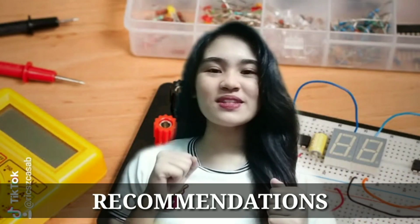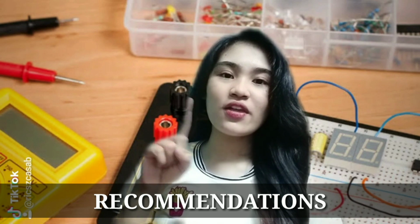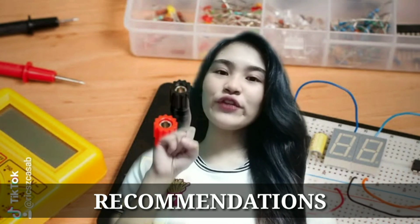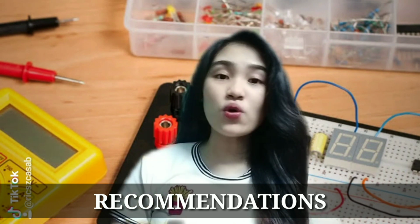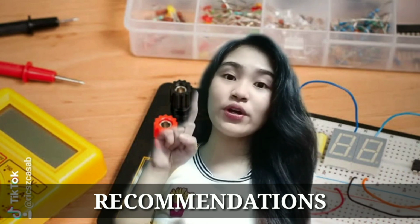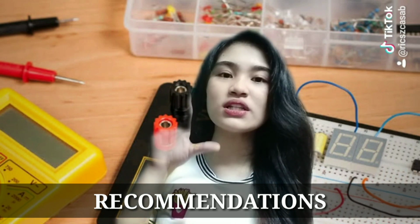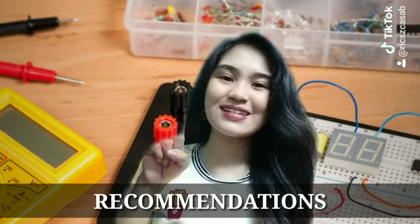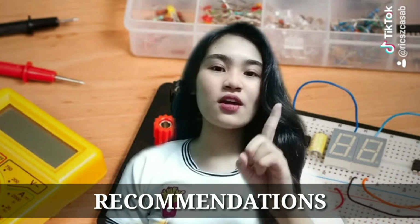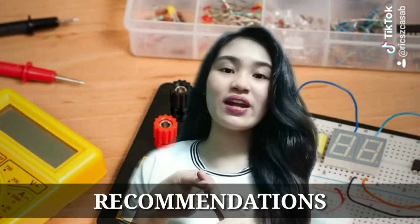Now, for our recommendations, please, to ensure that the circuit will be functioning, make sure that the connection is right. And don't forget the proper polarity of our integrated circuits or ICs. And also, don't forget the right connection of our relay to our voltage supply. Do not forget the 5 volts and the 12 volts supply because your motor will not spin if they are not connected. And of course, do not forget the right configuration of our transistor. The base, the emitter, and the collector should be connected appropriately.